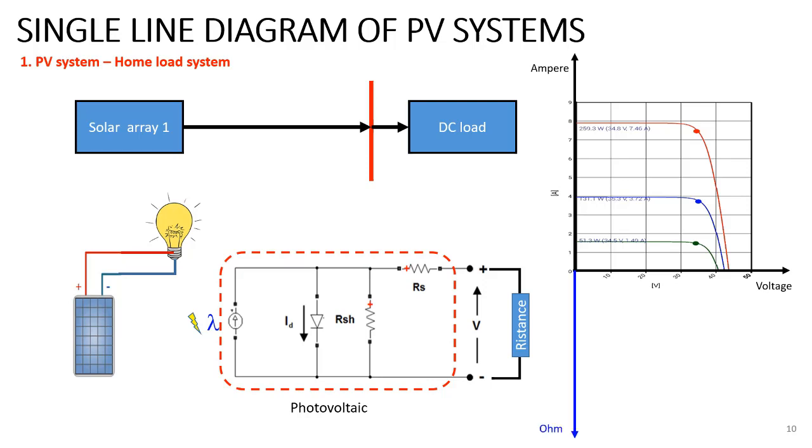We can develop the electrical response, the Ohm-volt curve, of the system with the use of the equation R equals V divided by I. Based on the IV curve and PV curve of the PV and the Ohm-volt curve, we can identify all working parameters of the PV at specific values of lambda and R.